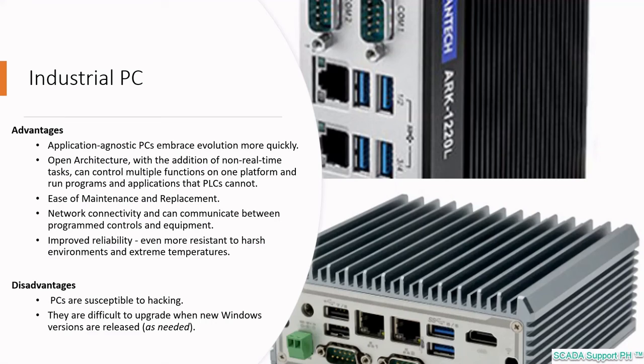There are also some disadvantages to using industrial PCs. If a server or PC is compromised and goes down, the PC-based controller will no longer be intact, functional, or operational. This can cause non-compliance issues with the PPA or IA. For Windows-based industrial PCs, if there's a need to upgrade the operating system, this can be difficult.